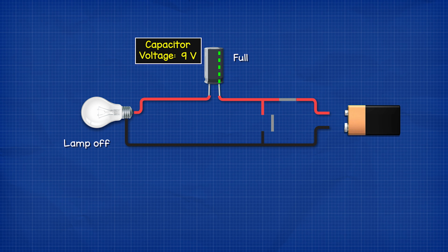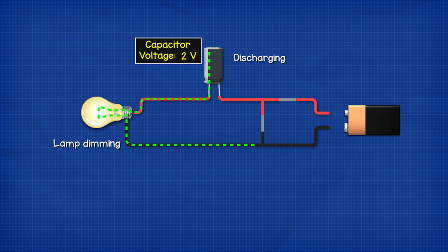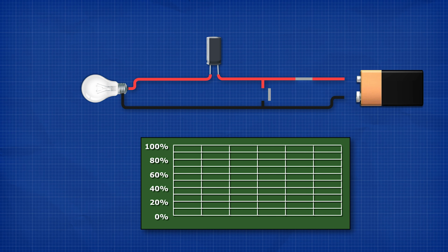When we provide a path for the capacitor to discharge, the electrons will leave the capacitor and the voltage of the capacitor reduces. It doesn't discharge instantly, but follows an exponential curve. We split this curve into 6 segments, but again we're only interested in the first 5.